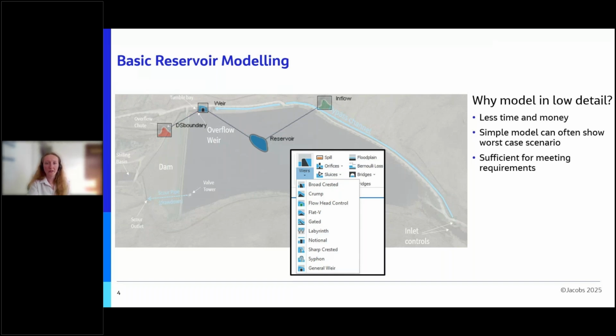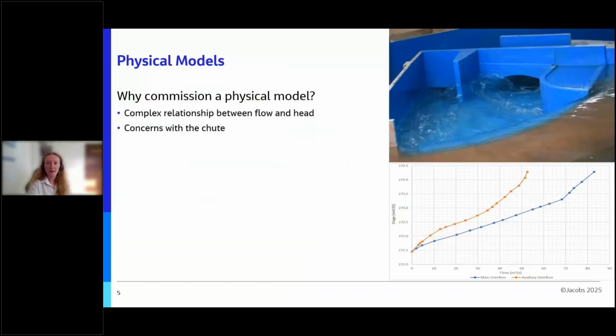Well, the weir equation works really well for flow in a channel, but the weir coefficient is fixed throughout the simulation. A dynamic weir coefficient is often more appropriate. In relative terms of depth to width ratio, the influence of the width of the crest becomes less, and it acts more like a sharp-crested weir with a higher coefficient. This is where physical models come in handy in cases where the relationship between flow and head is expected to change significantly at a certain depth above the crest.